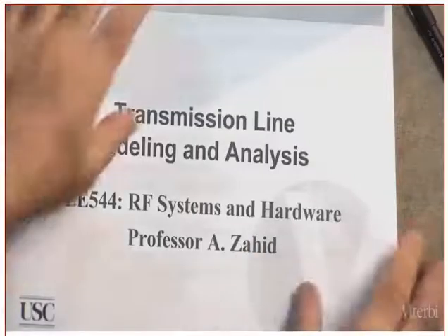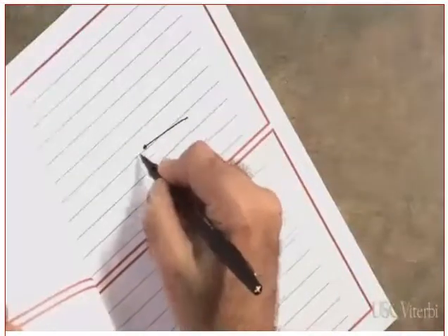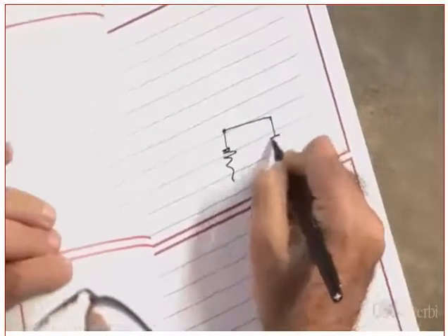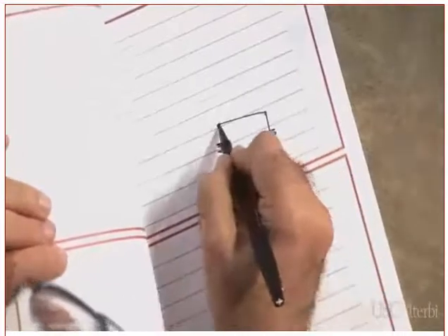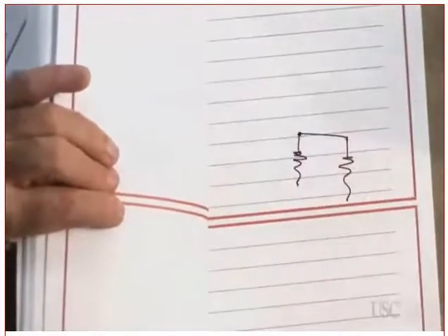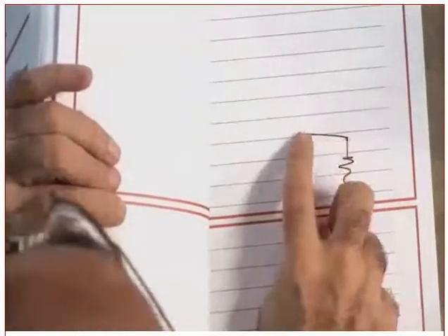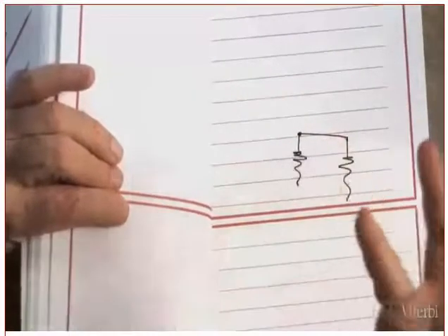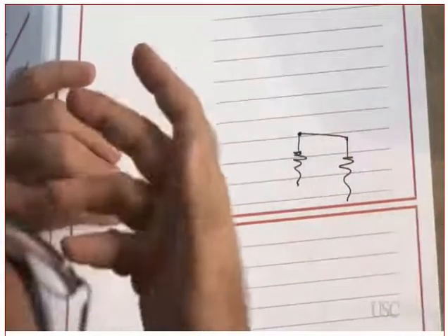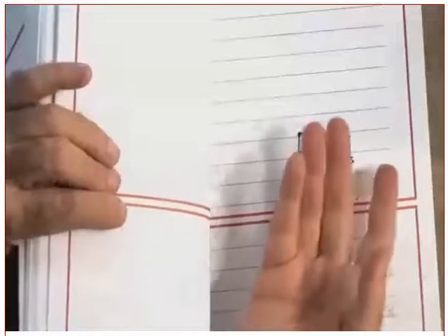What we were saying is that if I have in a circuit, let's assume that I have in a circuit like this, and then what here? Another component. Answer me the following question. Is the voltage here the same as the voltage here? But we discover that if we put here a transmission line, and we increase the frequencies to the RF, this voltage and this voltage will not be the same. Do you understand that or not?